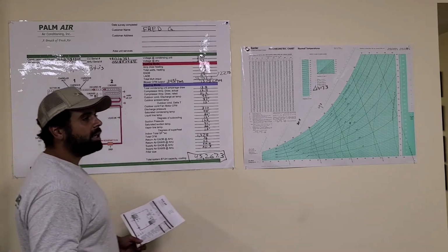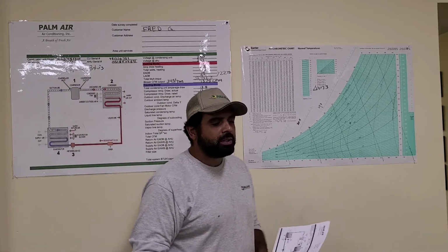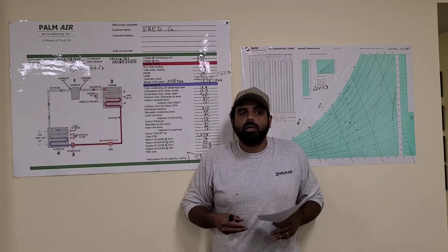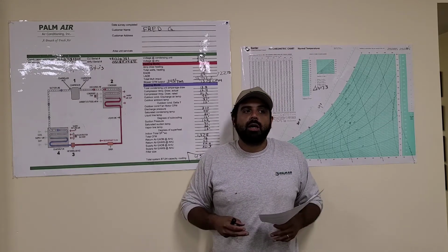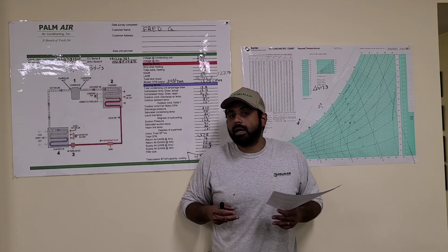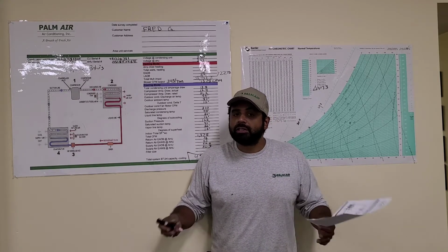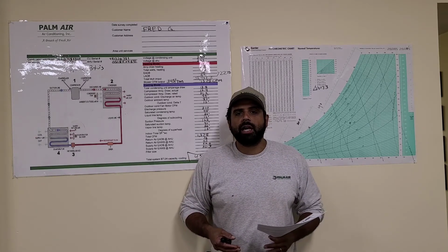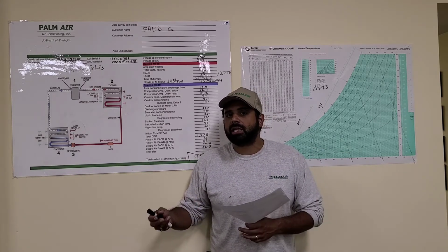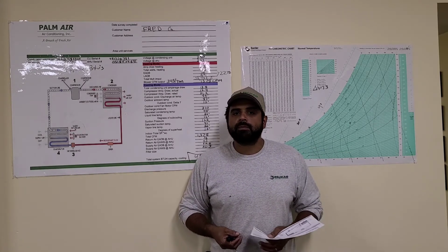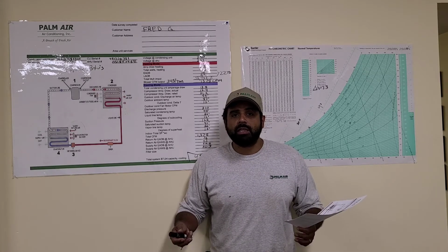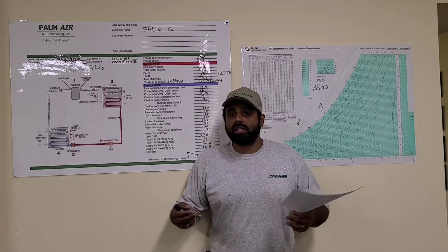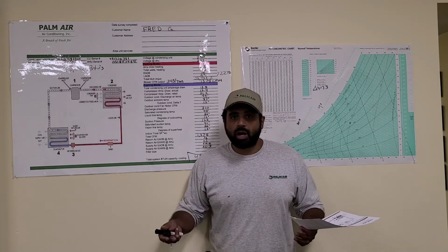So I wanted to go ahead and talk about one last one. Often we hear, especially as we're putting in the newer, more efficient equipment, which is actually designed to run longer to provide additional dehumidification for the customer at a lower amount of electricity output, I also oftentimes get customers telling me, I feel like the new air conditioner is running longer than the old air conditioner, and therefore in the customer's mind they equate that to costing them more in electricity. However, if we've cut the amount of electricity used in half and increased the amount of time by 25%, there's still cost savings in electricity.